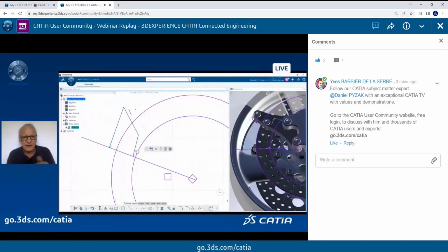Very nice capability. So I start my sketch. As you see, here I can also use the menus or the commands which are in the action bar, here on the lower level of the screen. This is typical design of my sketch. I define some constraints, some offsets. I define some fillets. I will also mirror this half sketch because I would like to have the complete sketch. And you see, I do not click. My mouse mileage is very limited.